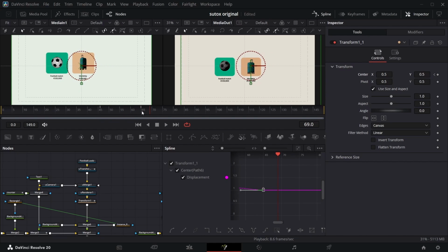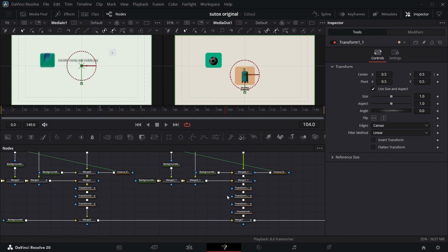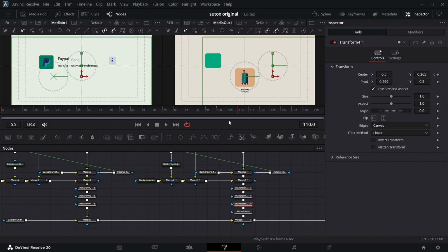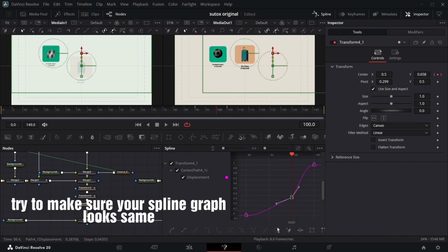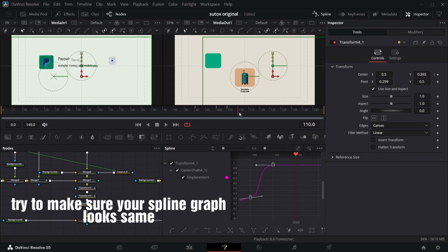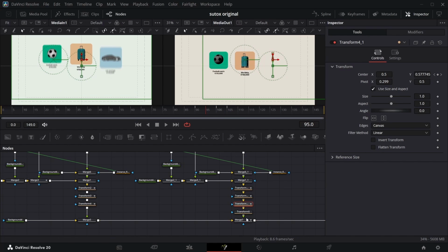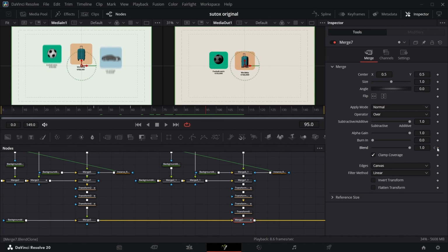I think that is fine. And so we have a problem. We have not smoothened this. Okay, it's this one. So let's take this one to spline. Yes, go to frame 95, come to this match node, keyframe the blend value again because we did keyframe it before, and go to somewhere around frame 101 and just take it down to 0.